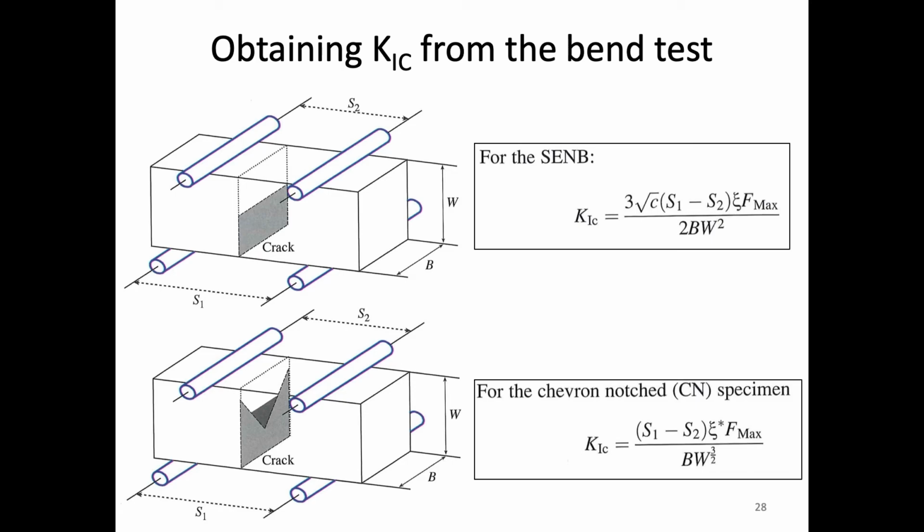where we take a material and put it under a mixed stress state, where it's being bent either by 3-point or 4-point, and this causes tension and compression depending on the location. And this is one way that we can test ceramics. So we can do a modification of that to get K1C. K1C is all about a material's response to a flaw.